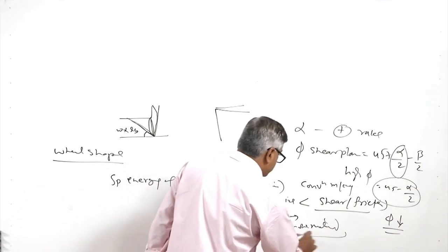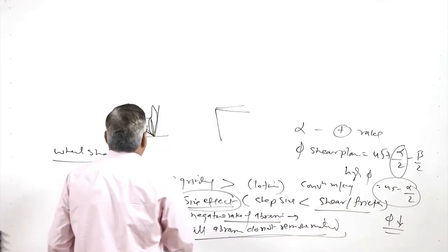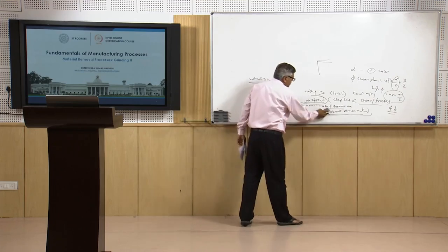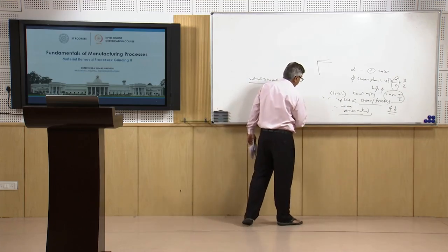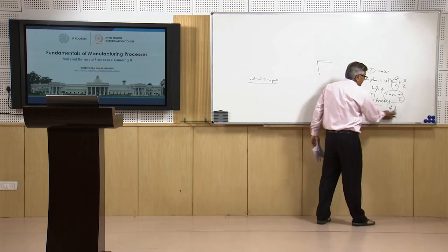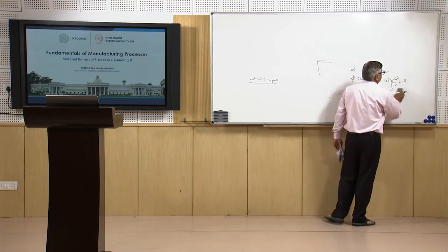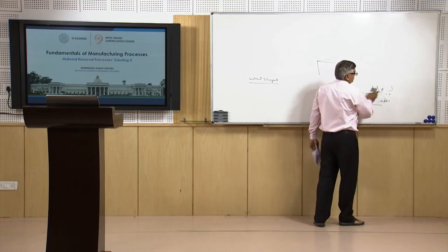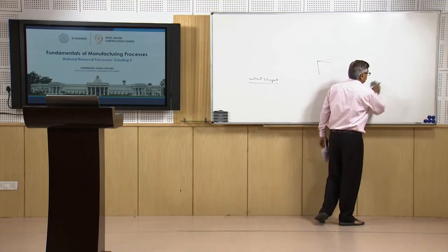And all abrasives do not perform cutting. This is a very important aspect related to grinding, and it is an integral feature of the grinding process itself, which leads to somewhat reduced removal of the material, as not all abrasives participate in the grinding process.